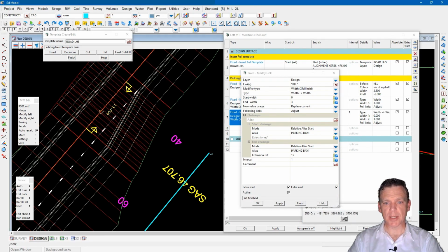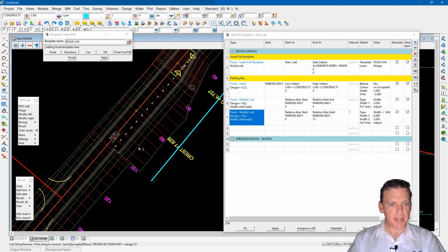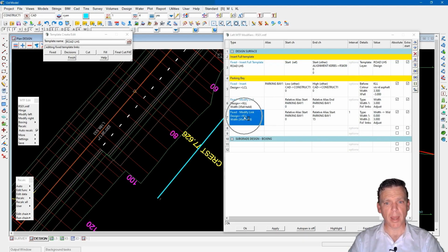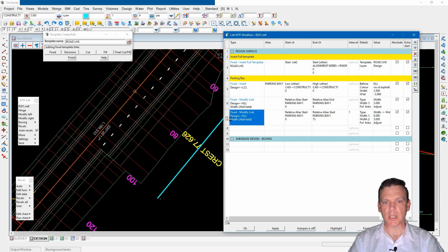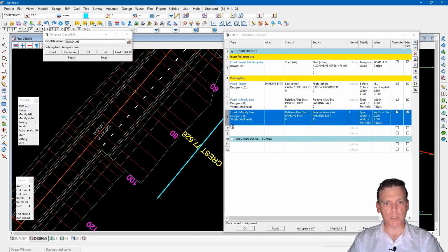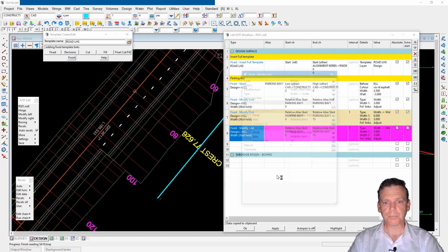The end transition is very similar. It's just in this case, we need to go from a width of 3 meters down to a width of 0. And because I've already got everything locked in here, I know the name of the string, the design curb lip line, I know where I'm going to do this, and that the widths will change. I could actually copy the command, do a right mouse button copy or Control C on the keyboard, and obviously paste it in for the third line.